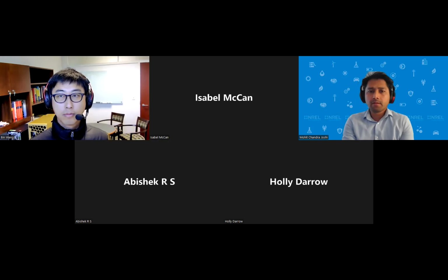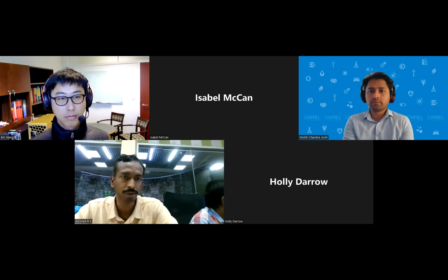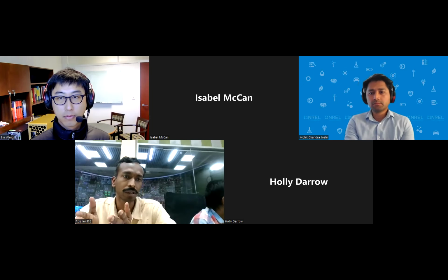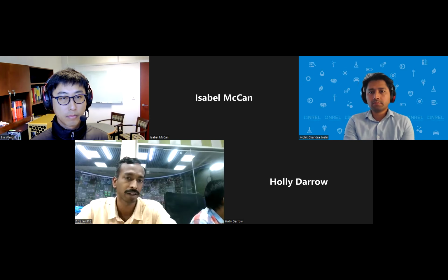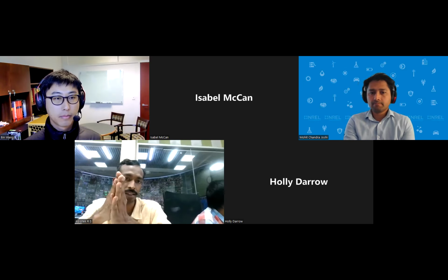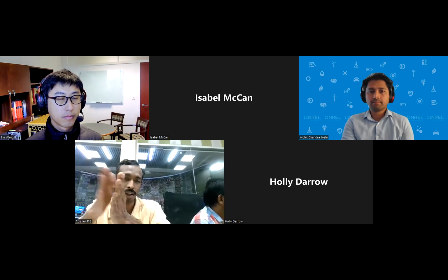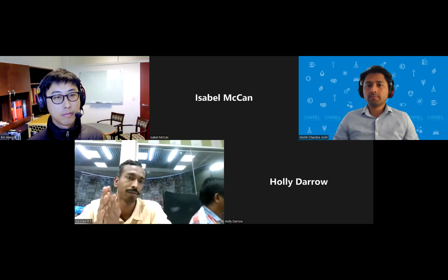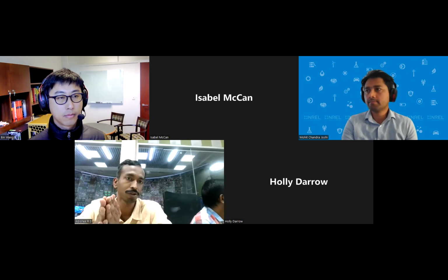Yes, 5 seconds is good enough. It can be used. There is no issue. The smallest time window is limited by the PMU sampling rate, 25 Hertz. It's a moving window FFT. It will just see where the FFT value is more than the threshold. If it is more, then it will be flagged, and it checks for consecutive scans where it is more. The longest set of consecutive scans will be the window. So there is no limitation on the size. It is limited by the PMU sampling rate. So 5 seconds is very comfortable. It can detect. No issue with that.